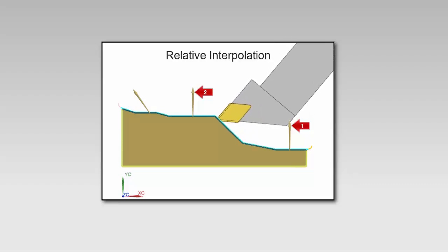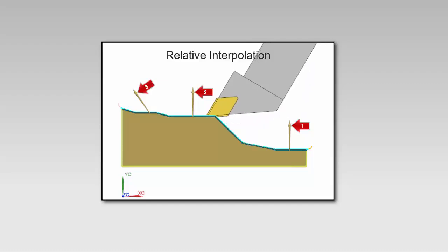As before, vector 3 has a different orientation, but the tool now gradually changes its B-axis orientation to maintain a consistent orientation relative to the part as it moves toward and aligns with vector 3. There are no additional vectors, so the tool continues to maintain a consistent orientation relative to the part as defined by vector 3.